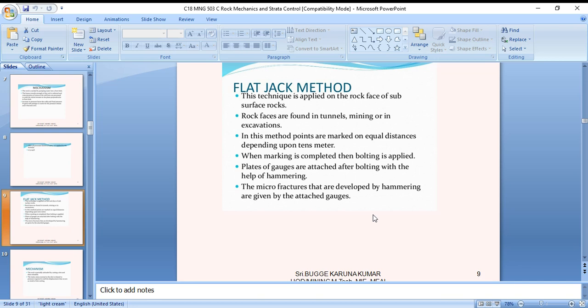There are two kinds of instrument errors, random and systematic. Random errors, of equal probability, may be positive or negative within a spectrum around the true value, and may be caused by factors such as friction or lost motion. Random errors tend to average out if a sufficient number of measurements are taken.